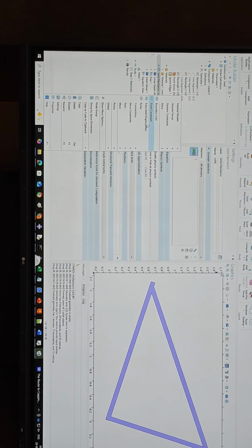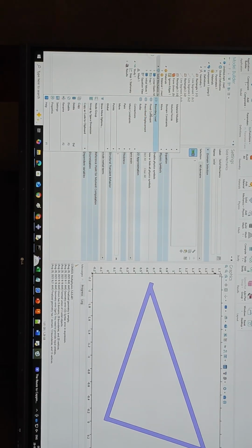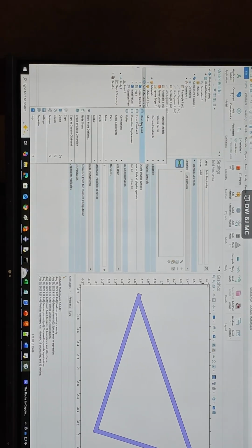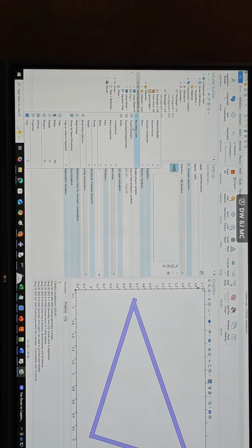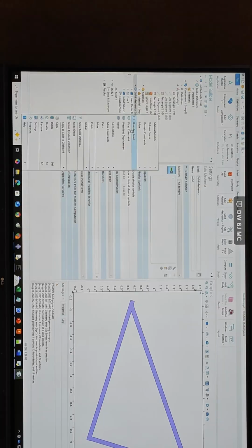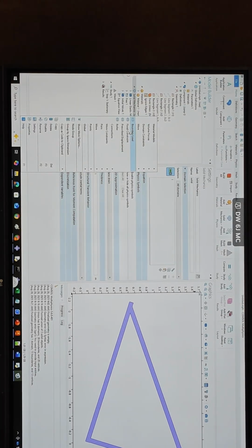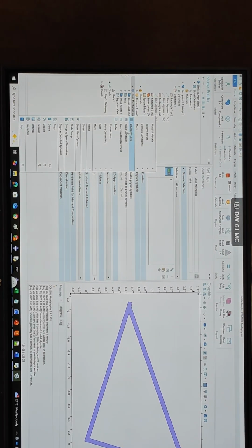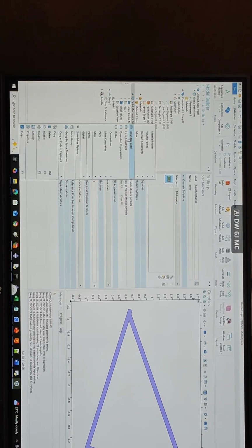Now here we have the boundary conditions you want to give, the fixed constraint. You can use a roller, I just prefer using prescribed displacement. And then you have the boundary load. So all three required. Now let's say you want to give it at a point. So for 2D, a boundary means an edge and a point means that vertex. And in 3D, a boundary means a face and then a point will still hold its same context in 3D. So that's a small difference between 2D and 3D when you move.